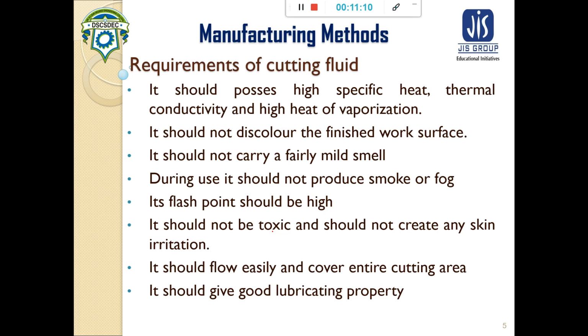Next, during its use, it should not produce smoke or fog. That means its flash point should be high. During the application there is heat, and there is a high chance of smoke forming. That smoke forming shouldn't happen in the case of the cutting fluid.